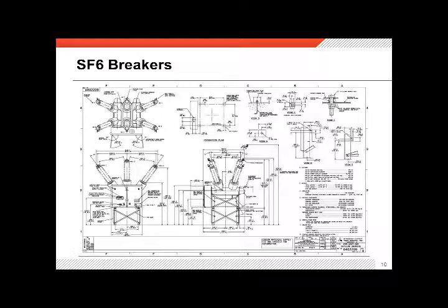All right, moving on down to the lower left. This is a view of the circuit breaker from the front. Again, you can see the control cabinet and quite a few features therein. And then you also have a side view here, and it shows how much space you need to have in front of the control cabinet. But it also shows a couple other things. This dimension over here is the amount of free space that you have to get the interrupter out of the circuit breaker if you have to replace it or do maintenance on it.